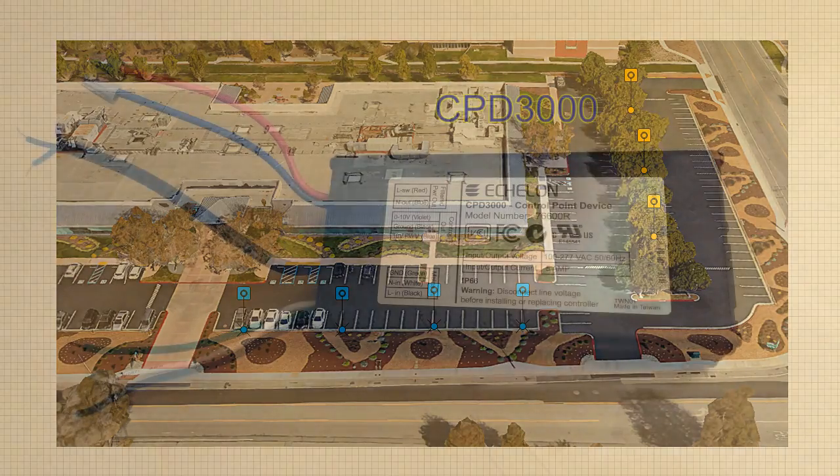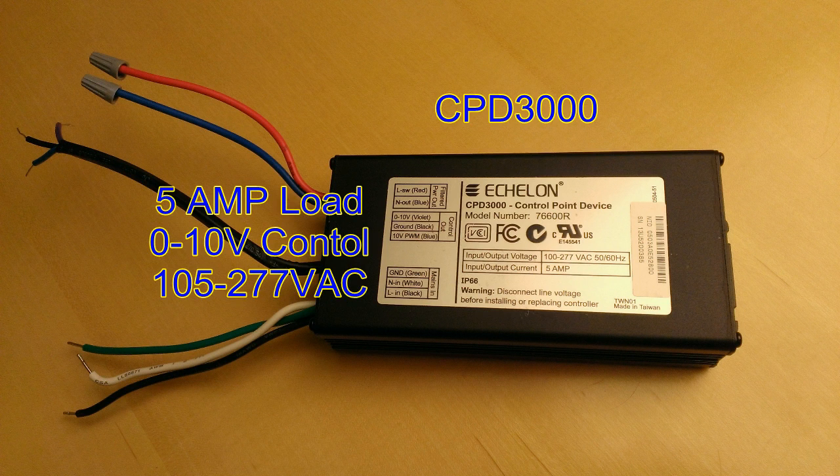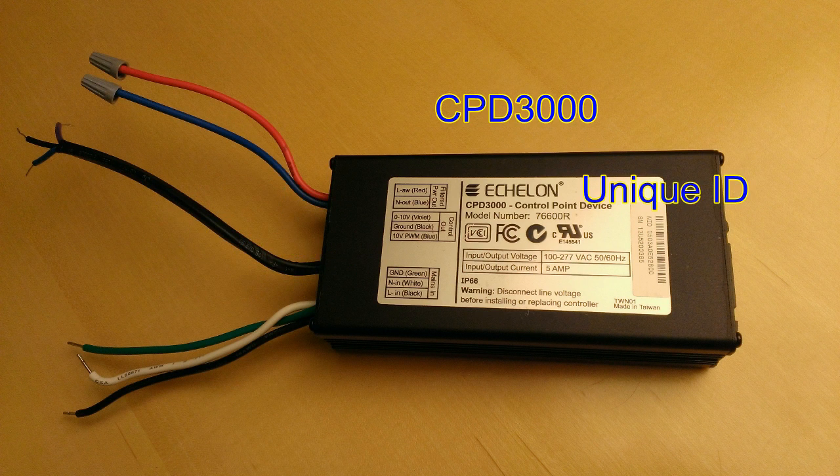The workhorse of the outdoor lighting system is the LumaWave CPD 3000 Outdoor Lighting Controller, or OLC. It communicates operating and fault data over existing mains power up to 277 VAC. It switches loads up to 5 amps and will dim fixtures that support a 0 to 10 volt control interface. Each device is uniquely defined by its unique ID.